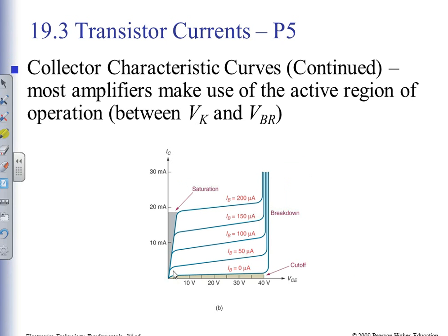So here we are, and we're doing it in 50 microamp ratings, and we're finding where breakdown occurs. And we can put the transistor in breakdown without breaking it, but if we go too far, it'll melt it. So what happens on the tester that I have, it'll actually send it into breakdown. You can see those lines go up, but you limited the power so that you don't burn it up.